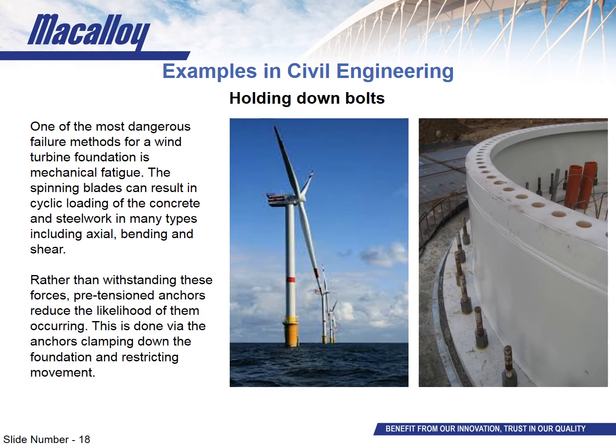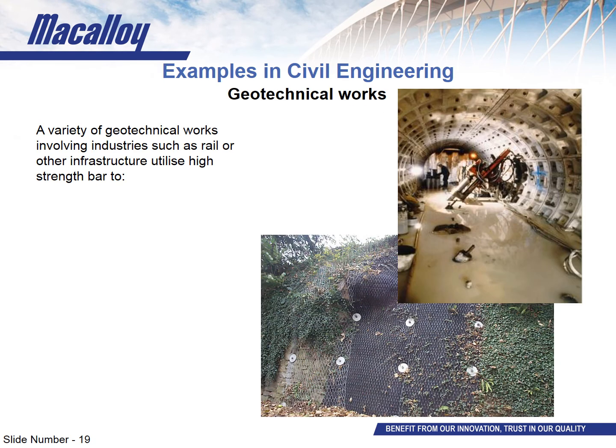As with the last example, preloading the bolts in the foundation actively clamps it down, both minimizing movement and reducing any likelihood that the stress in the bars will significantly change. While beneficial, even preloading cannot completely mitigate fatigue demands, so a tested, fatigue-resistant product is necessary for complete assurance of performance.